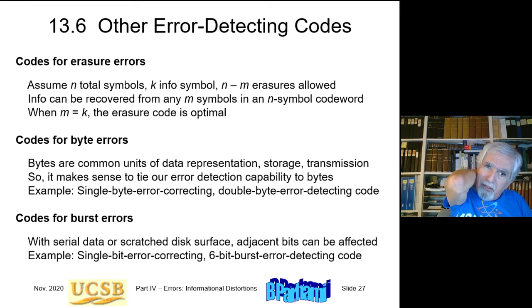If you try to compare it to lying, if you talk to somebody and that person does not respond, you get into less trouble than if the person responds but gives you the wrong answer, okay? For erasure error, you just don't know what that particular bit or symbol is, but you don't get misleading information, okay? So erasure errors typically involve less redundancy and are easier to deal with.